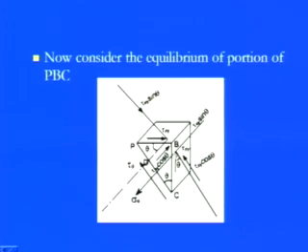So, you can find these components, the tau xy cos theta and the tau xy sin theta, which are the resolved forces at the theta angle. We have the tau xy, which is set up on this plane, you can see this is tau xy, this is tau xy.